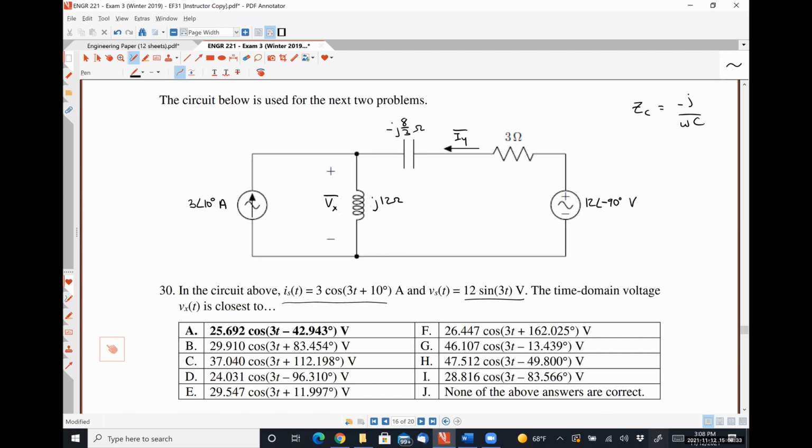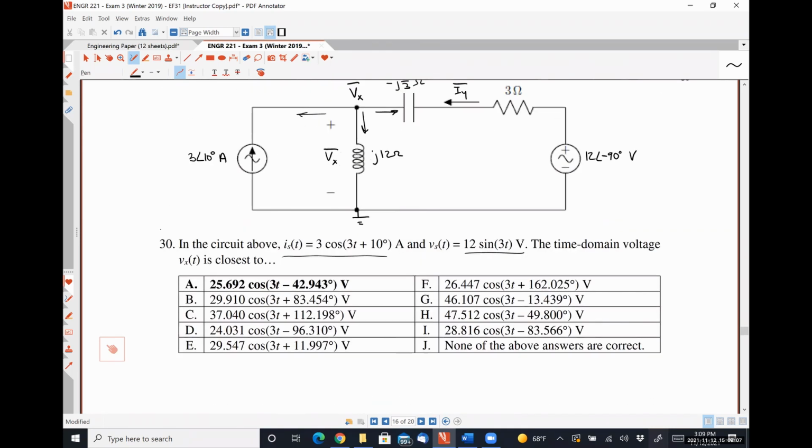All right, so for this particular circuit, I would actually do nodal analysis with air quotes. If I called this guy ground, this voltage right here is also Vx, because Vx is simply the drop over my inductor. And so I could apply Kirchhoff's current law, meaning I would need to know this current, and this current.